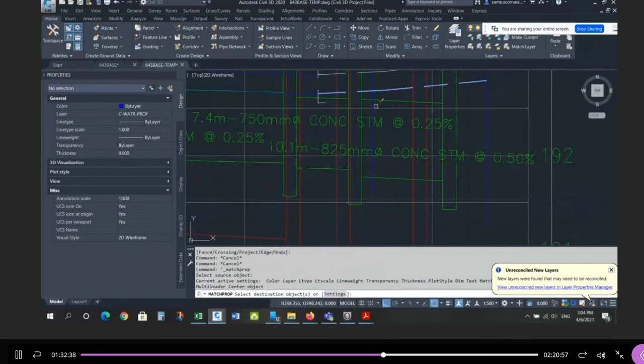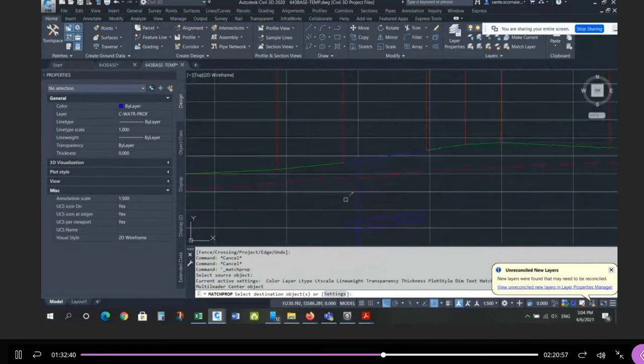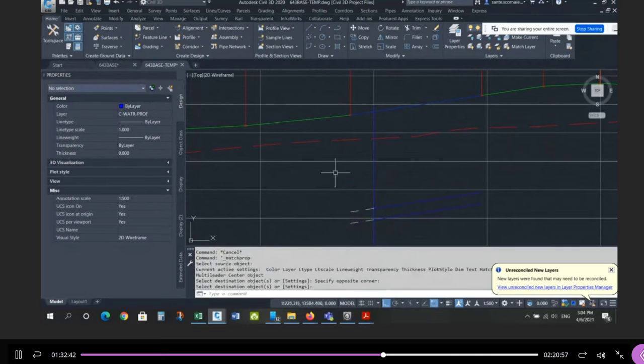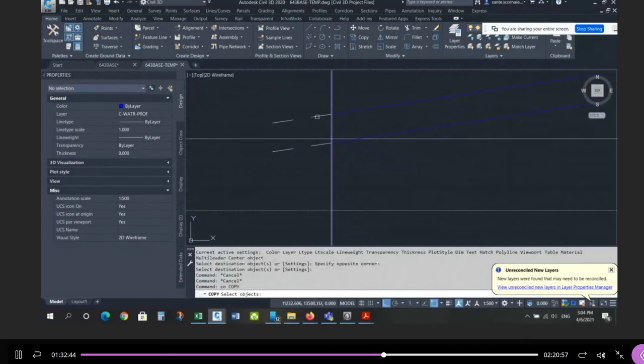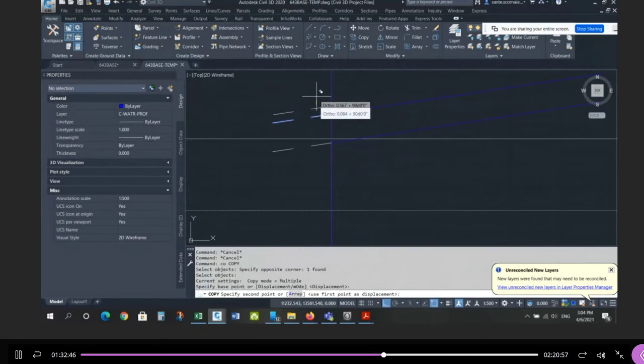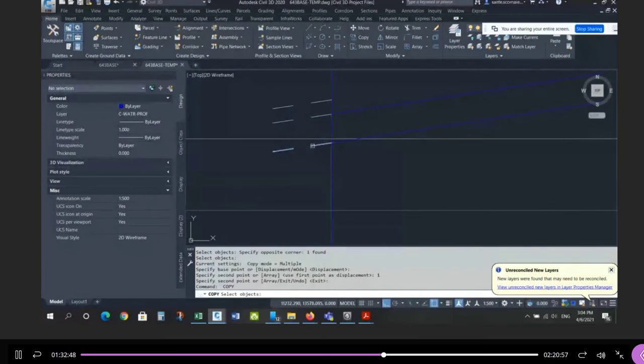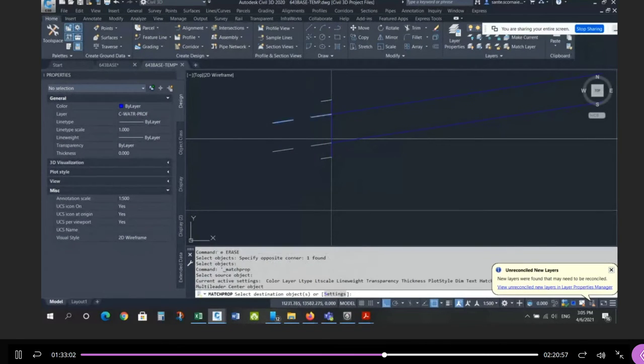It's supposed to look like this over here. Then you can use the same technique I had. Take this straight up 1 meter, take this down 1 meter, offset this 0.75, trim, get rid of this and make it all existing. There's your plug on the water main here.